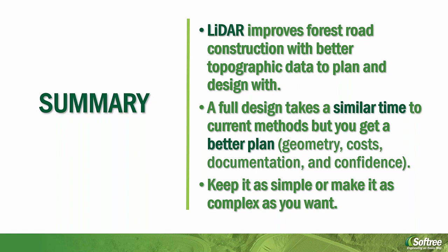Of course, a lot of you will want closer constraints than that, so you can flag it in. If any of you are familiar with it, you can still use a P-line for reference, so you can have your ribbon center line and give offsets relative to it if need be. Then if you want to go really fancy, you can use a total station or RTK and slope stake everything. So it really just depends.